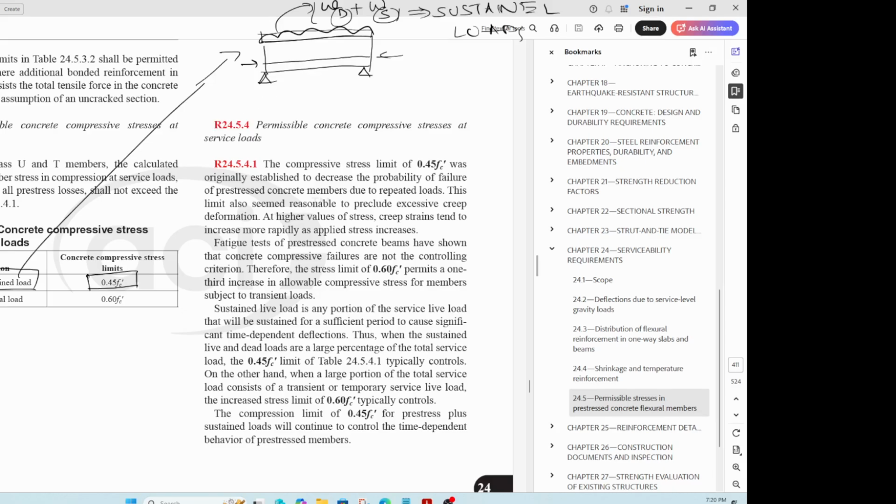The next row in this particular table is pre-stress plus total load, and the total load scenario is divided into three categories. One is load caused by your dead load. That means you have already installed a slab on the pre-stressed girder, and you have the self weight of the girder acting obviously, and then you have opened the bridge for traffic, so you have a live load component.